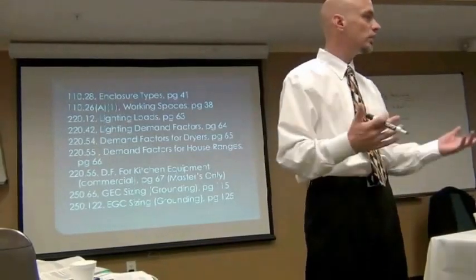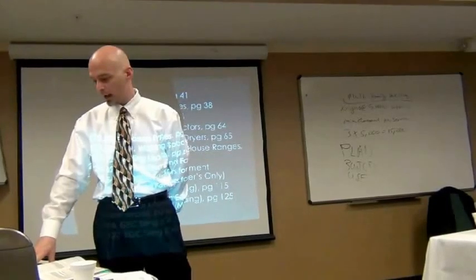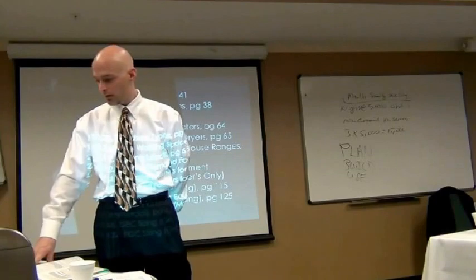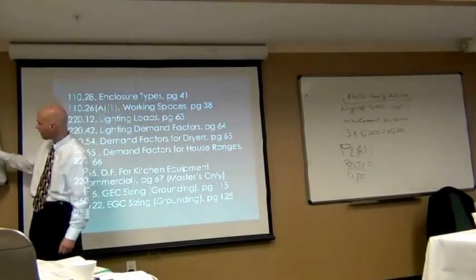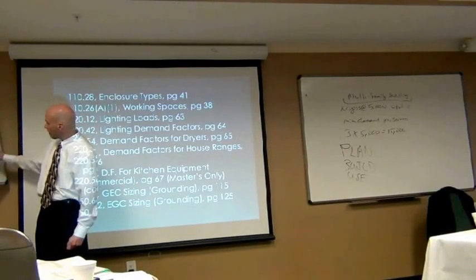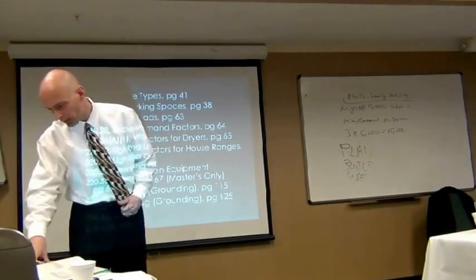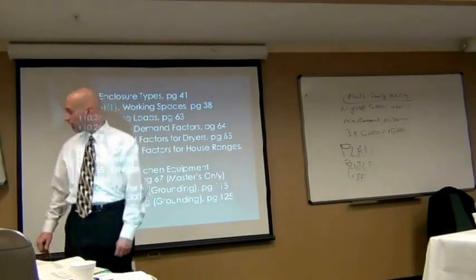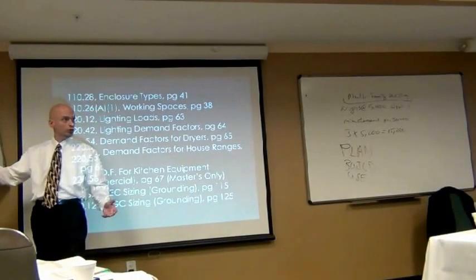Forget note B. Let's just say you normally would just go by the table. Well, you'd have to take the group, which is 50 amps. Look at the table there. What's the cutoff for number 10? 60. So I'm actually okay with the number 10 as far as that size right there. But all of these conductors here, if I have to increase that number, let's say, what would I normally have for that 50 amp? Let's say it'd be a number 8, right? So I would normally put a number 8 in here for this 50 amp, but I've actually increased it to a number 6 because of voltage drop, right?